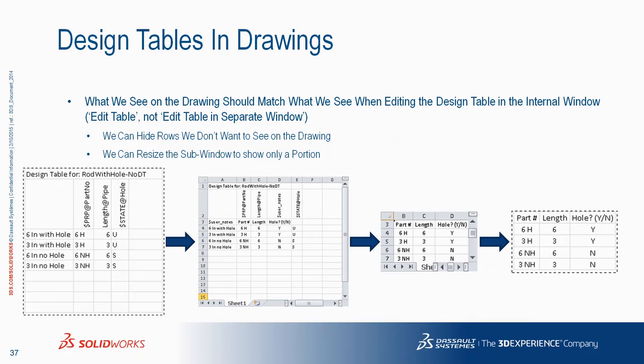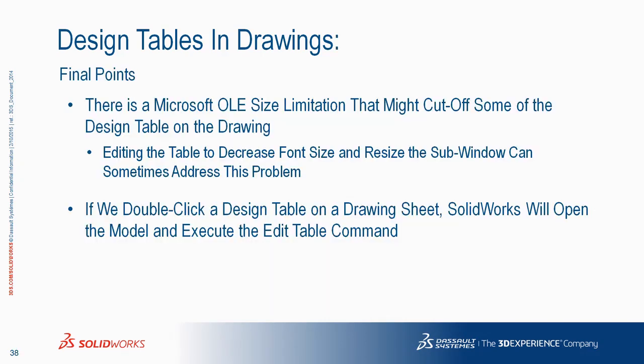Yeah, that is, and that's something that guys definitely put out. If that's something that you want to do and you have a problem with, put out an enhancement request to SOLIDWORKS at that point in time. Contact your VAR, put out the enhancement request, because that's the only way that these things are going to get changed inside the software. I've been doing this presentation a long time. Ever since I've been doing design tables, it's always been set up this way. That is the only option for controlling what you see, short of saving out a copy of it, but then you've broken the link at that point in time.